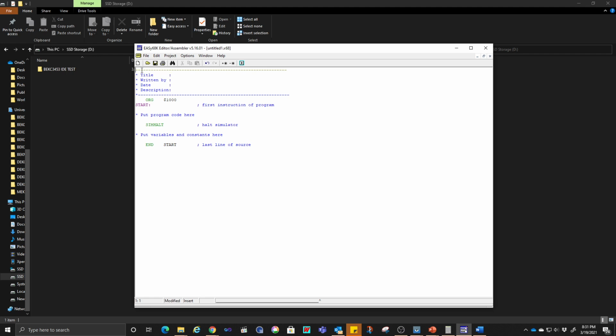So you must have this one, because if you want to put notes or names or whatever comments at the beginning of the lines, you must have this asterisk symbol. Same goes if the comment is after the syntax, you must have this semicolon.